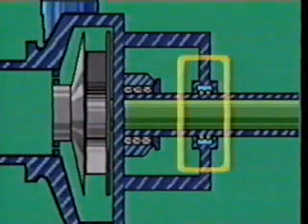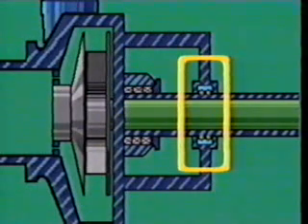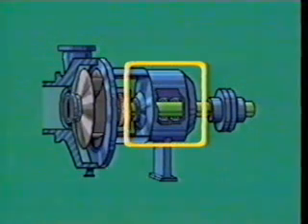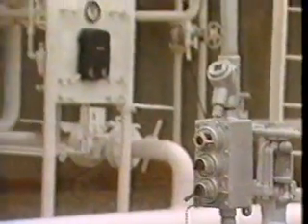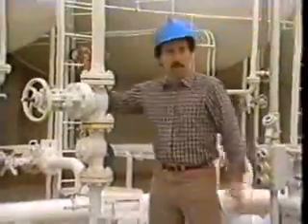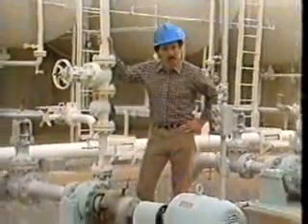Bearings can be here, in the pump casing on small process pumps, or separated in special housings on larger ones. Last, are seals, or packing. They're used to stop or cut fluid leakage around the shaft.